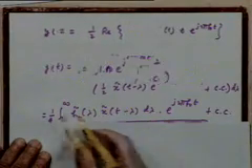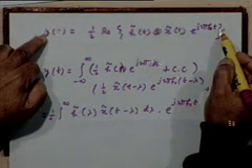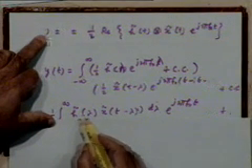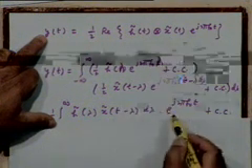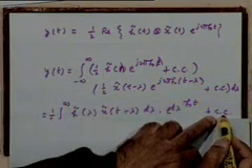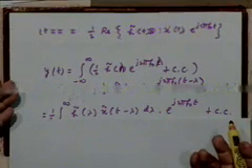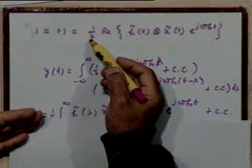What I am saying is that these two terms are equivalent to writing this, right? This is nothing but a convolution of h tilde with x tilde, which is what I have written, into e to the power j2 pi f naught t. And since you are adding a complex bit of that, what are you doing? You are taking the real part of that, twice the real part.